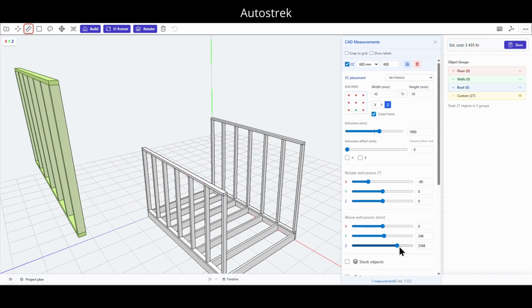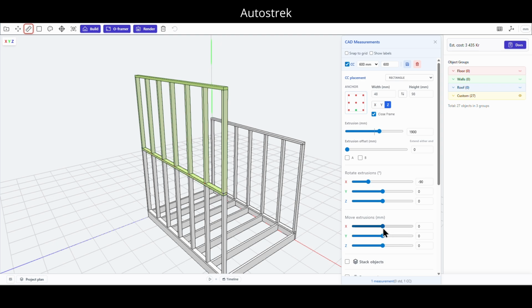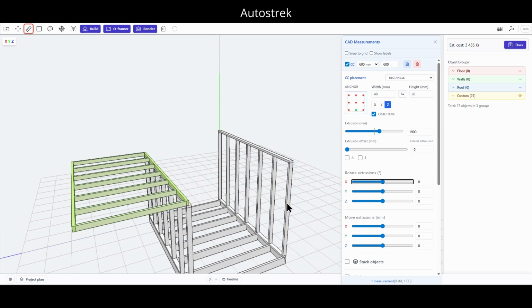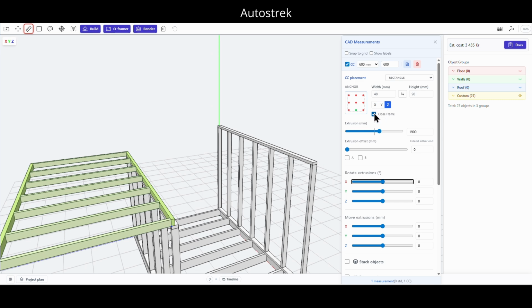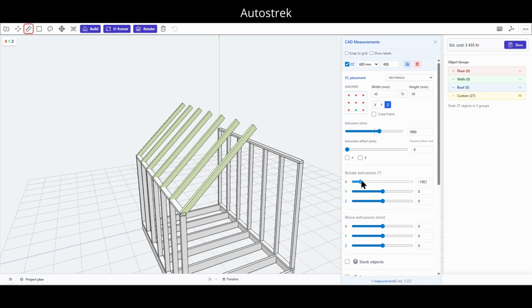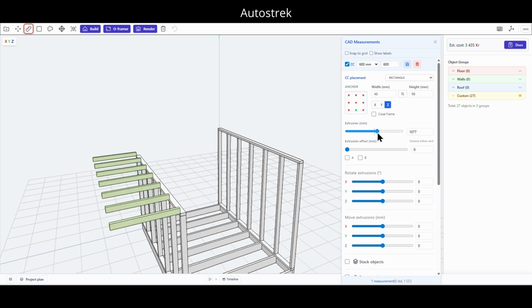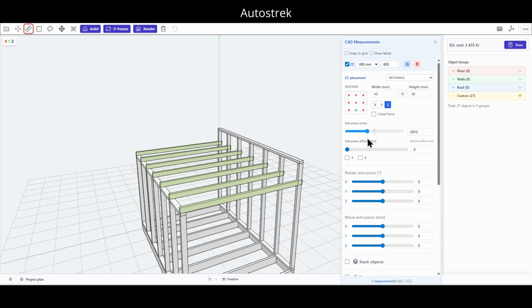If you double-click the small dots on the sliders, they reset to 0. It's much faster than nudging back manually. Instead of rotating nearly 180 degrees and ending up with a confusing angle, you can simply switch the extrude direction and use a rotation that's easier to reason about.